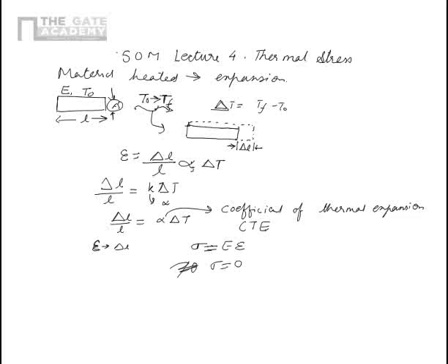Now when the molecular structure changes, it causes a realignment of the crystals, or in case of polymeric materials, the chains of molecules, which causes the increase in the length. So please remember, in case of thermal expansion, if the expansion is free, which is that there is no resistance to expansion, then there is a strain, but there is no stress in the material.